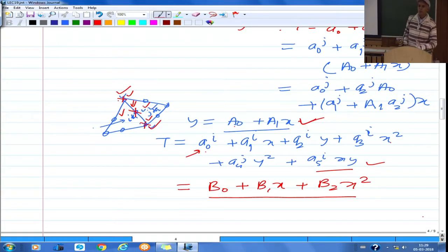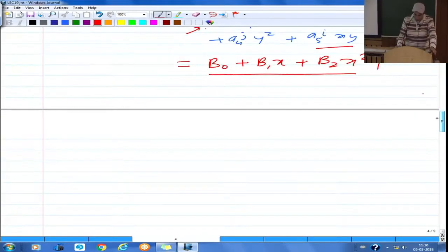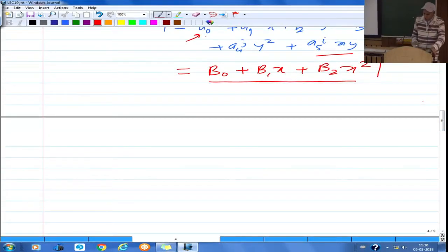So this 6-noded triangle, formulated in the physical xy coordinate space, also satisfies the continuity of T in this case, if T is there as degrees of freedom at the nodes of the element. Enforcing the continuity first of the values of T at the node points, it will then also be the same along the entire edge.